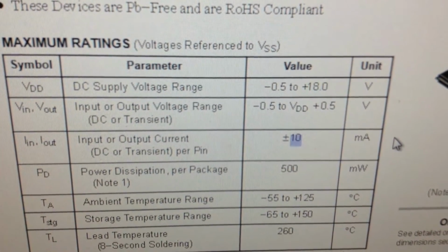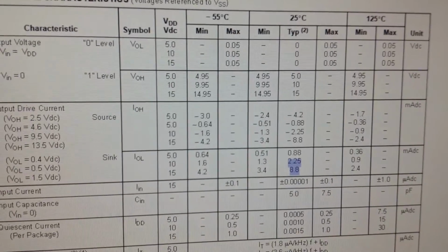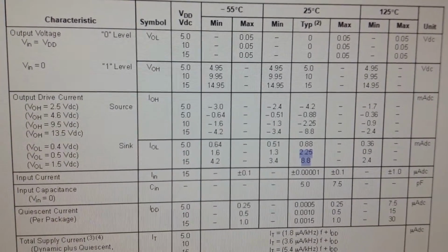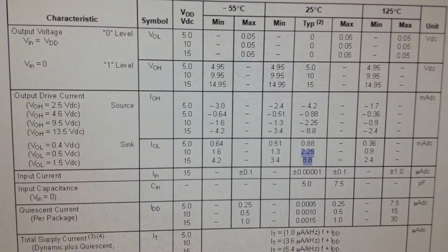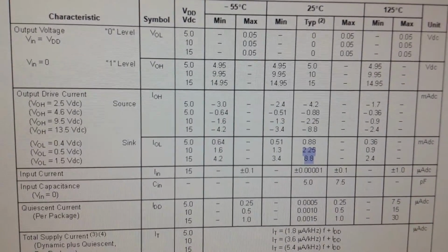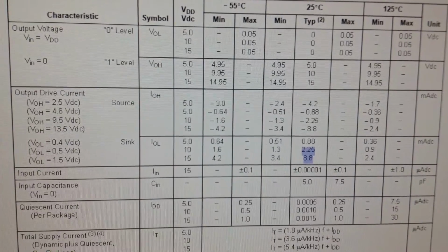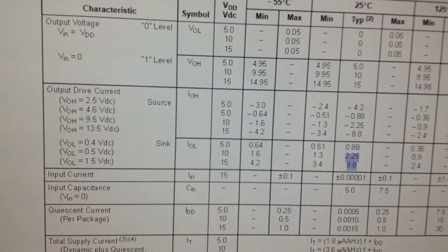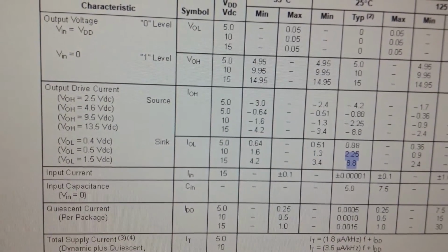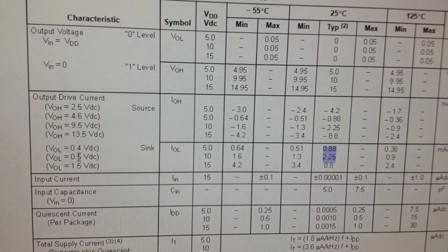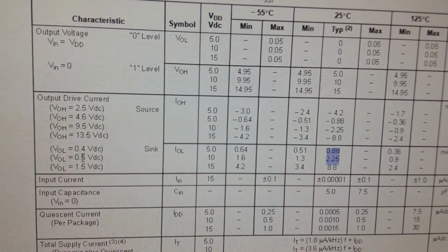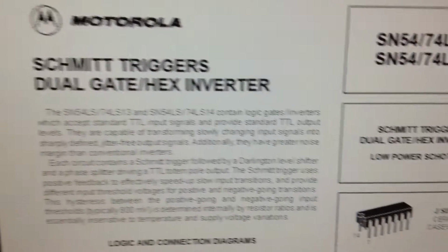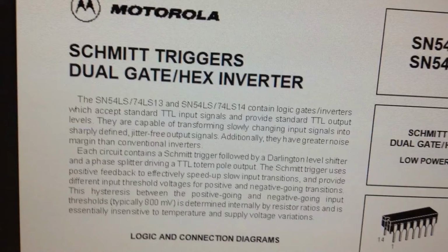And furthermore, with the drive attached, we are expecting 6.5 milliamp draw from the pull-ups. That's 5 milliamp to the drive and 1.5 to the C64. Here you can see we are somewhere in between these two conditions, and the output low voltage you can see on the left isn't very good. Somewhere between 1.5 and 1.5 typical. This particular chip is pretty old also, and by pushing it to the limit it will perform even worse. At 1.5 milliamp though, the voltage should be okay.